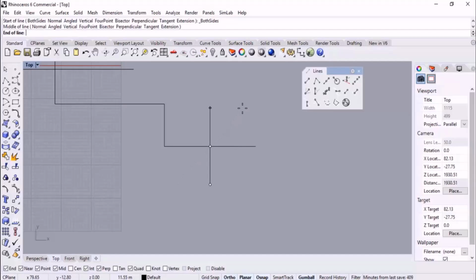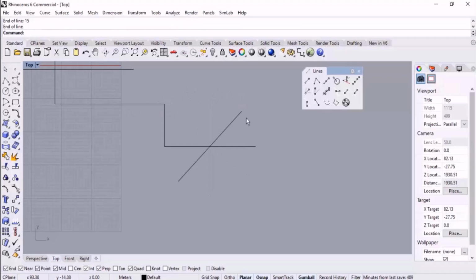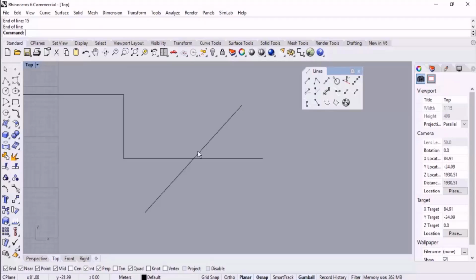And I have explained specifying the angles, for example, 45 degrees and 50 meters for length. At first the less than symbol, 45, enter, then the length; the angle is specified. I specify 15, enter, very well. Then I specify the direction, and this will be the result. The 15 degrees is related to half of the line, from the midpoint to the top part, and from the midpoint to the bottom, or the other end of the line.